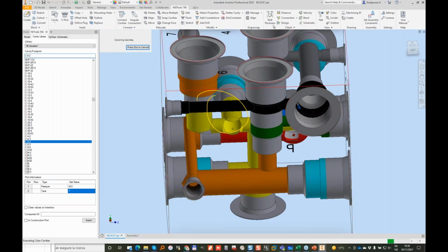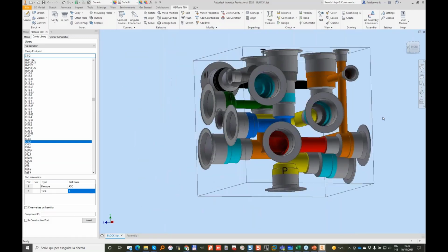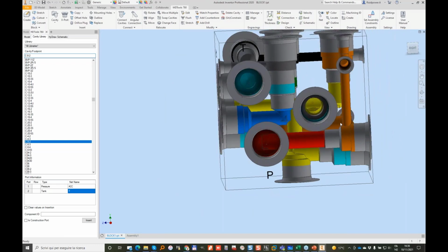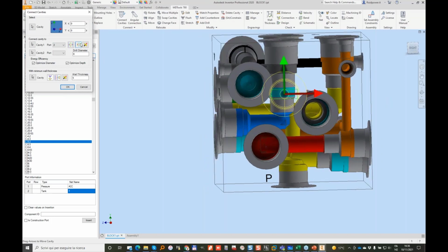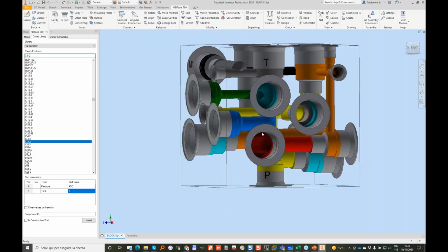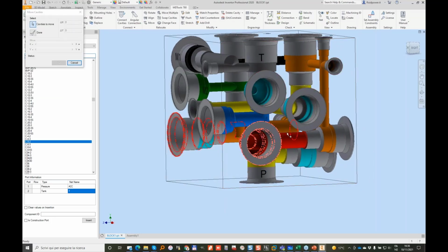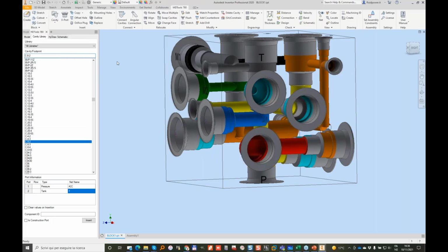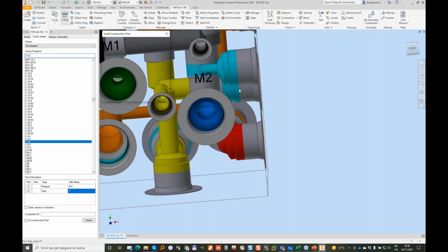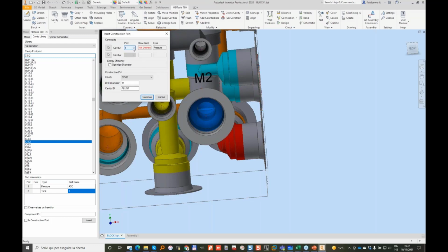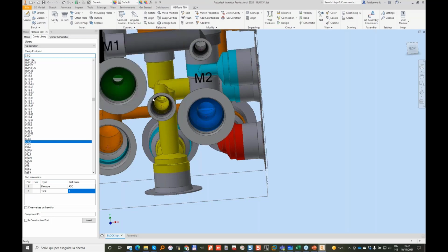Let me recolor and let me clean up my drawing. In terms of connections, I need the tank line. So I will connect my tank port with port number 2 here. A connection which is tangent on the opposite side. Looks okay. I will move down my P ports. The tank line here is not bad. I can just make a construction port on port number 2. Short port number 2.